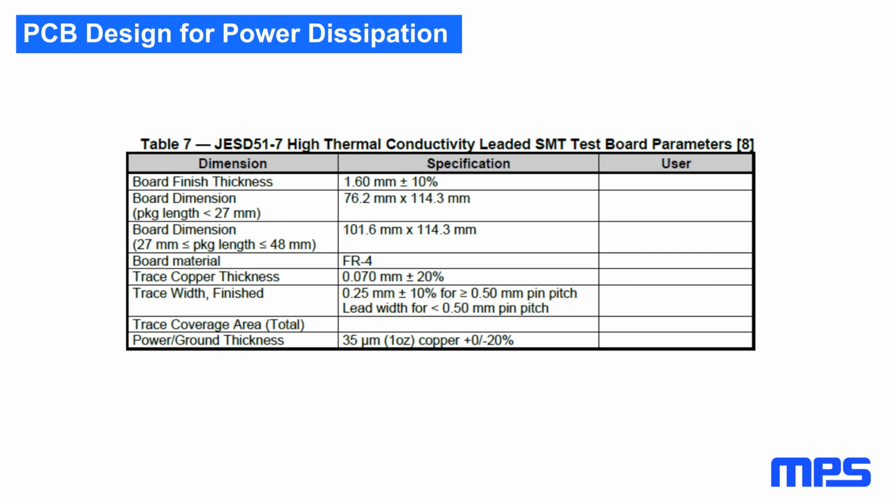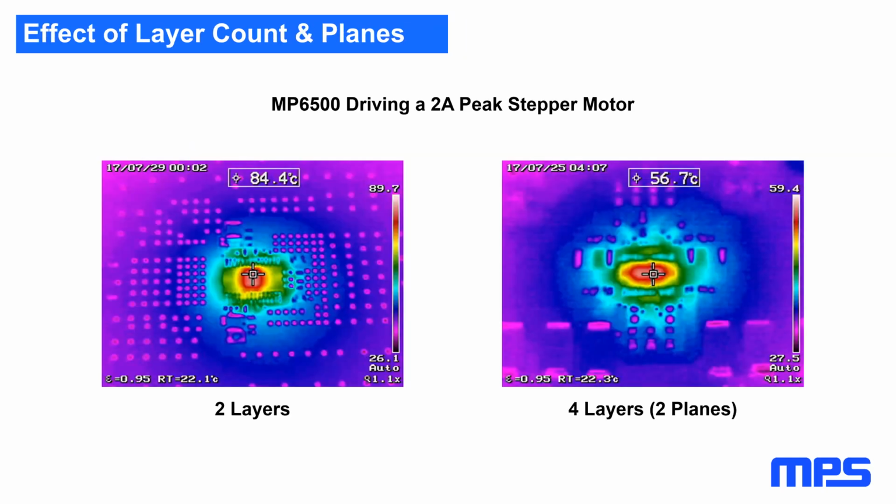If you're lucky enough to have access to thermal simulation tools, you can derive a pretty accurate thermal resistance. Otherwise, you have to estimate and make some educated guesses. There is a pretty big difference between a 2-layer board, where you only have copper on the outside, and a multi-layer board with solid planes inside.